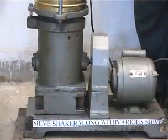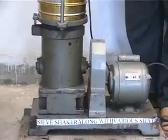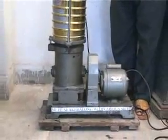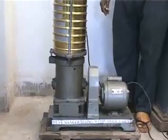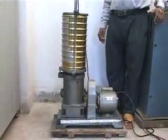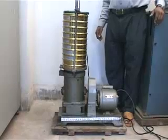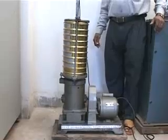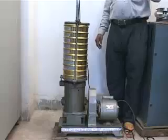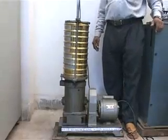Okay, now you see that we have put the sieve set that you saw earlier, on which we took 500 grams of soil sample, on the mechanical shaker, and we are going to subject it to mechanical shaking for about 10 minutes. After that we are going to find out the weight of soil retained on each individual sieve, and from that we are going to construct the grain size distribution curve. Okay, so we'll start the shaking now. You just watch it, and then we are going to come back to it.